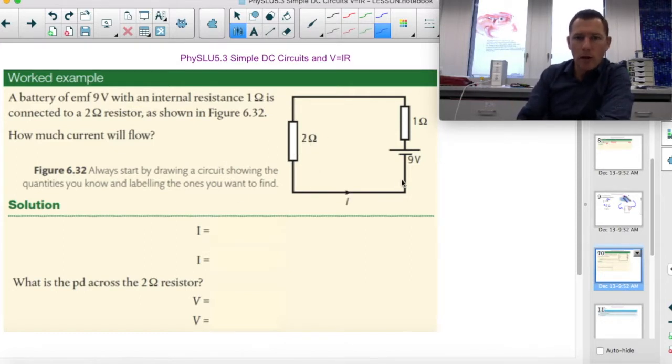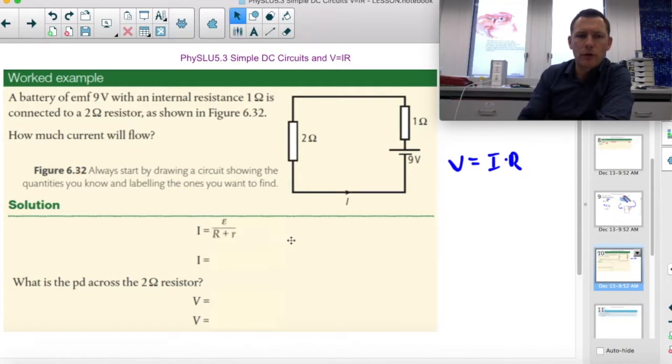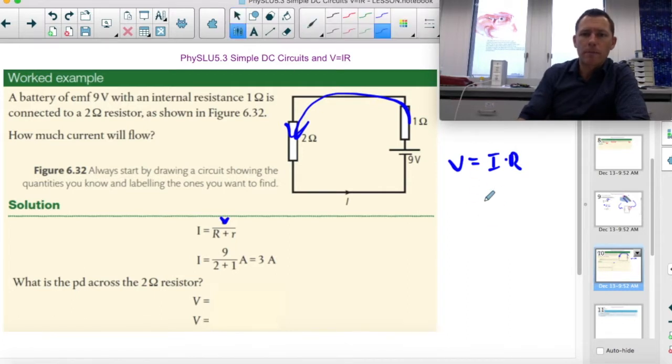All right. Well, I know that the pressure makes the current flow through the resistor. So we could talk about there being two resistors: this 1-ohm resistor and a 2-ohm resistor. In total, there's 3 ohms of resistance. So I'm going to call this V. I know there are subtle differences, but this is 9 volts. If we divide this out, you could say I is V over R. We have two resistors, a 1 ohm and a 2 ohm, so that's in the denominator, and so you get 3 amps of current coming through here.